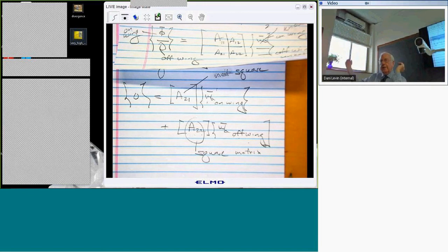So the method I just described for supersonic flow has a real problem when the Mach number gets too close to 1. You'll see a lot of plots where people have calculated flutter boundaries, and they have a calculated point at 1.1 and another one at 0.9, and maybe 0.95, maybe 1.05, but not too often right at 1. But they pass a curve through it and hope they get a decent answer. But in subsonic flow, we're really in the soup. So we've got boxes everywhere. So what are we going to do?